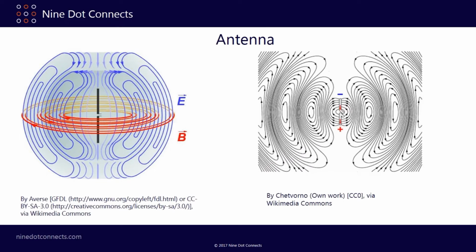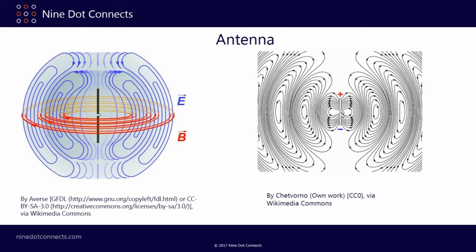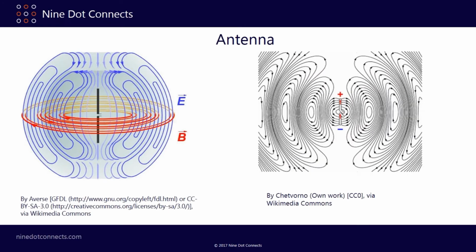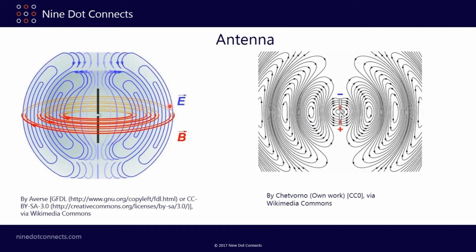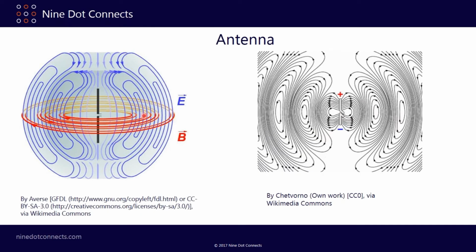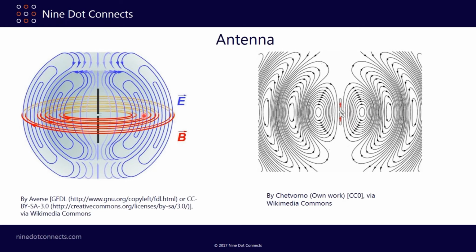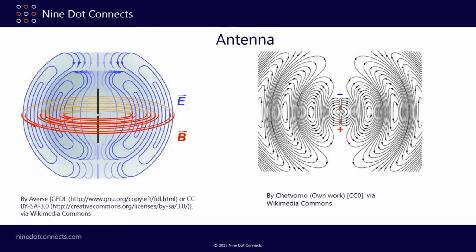And when that happens, this is what you get to see. These fields radiate out. And that's what the FCC test is looking for, is it's going to measure this electric field at a fixed distance away from that track that's on your PCB that's acting like an antenna.